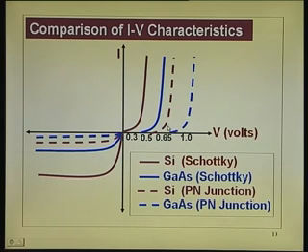You do not get 0.6; after 0.55 volts it becomes tougher and tougher, whereas in gallium arsenide p-n junction solar cells you will get close to 1 volt, a higher open circuit voltage. Okay. I will see if we have occasion to discuss some aspects of these things much later. So, this is what I want you to note.